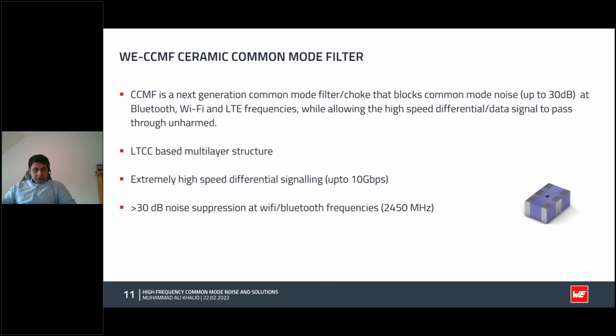The multi-layer design is made up of low temperature co-fired ceramic material, which is also known as LTCC material. The advantages of that material are that it is very resilient and has low losses in higher gigahertz frequency bands. The differential mode transmission and common mode suppression are controlled by the transmission lines in the form of metallization inside the LTCC material.